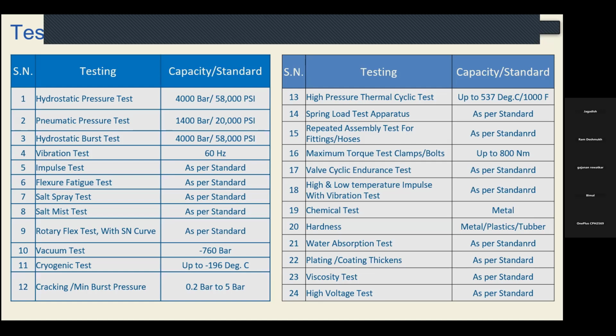And when we developed an installation manual for one of the products, a main criterion which comes into the picture is how you are going to define the torque or minimum force which is needed for the hoses. Yes, the standard says certain guidelines to be followed, but actually we need to decode what is the torque level, or what would be the associated force which is needed to connect the hose or tubes. So we have the maximum torque test, and those torque tools are basically digital, analog, or maybe load style kind of arrangement what we have. So we can help you develop the manual by which you can install your product at site.